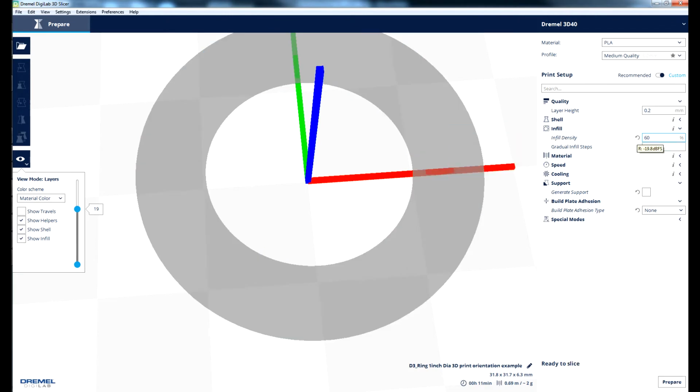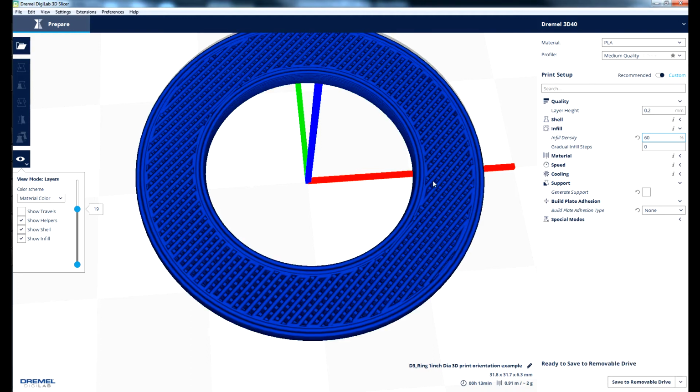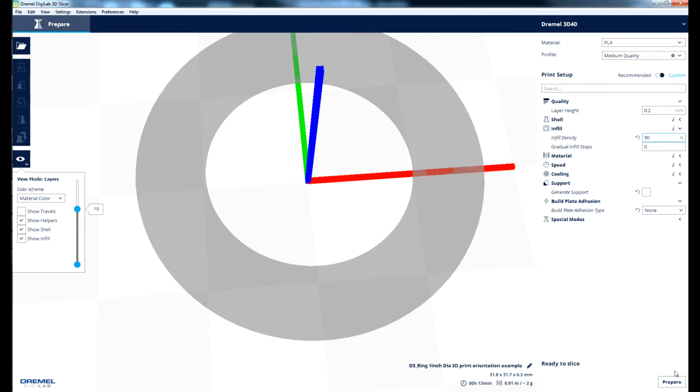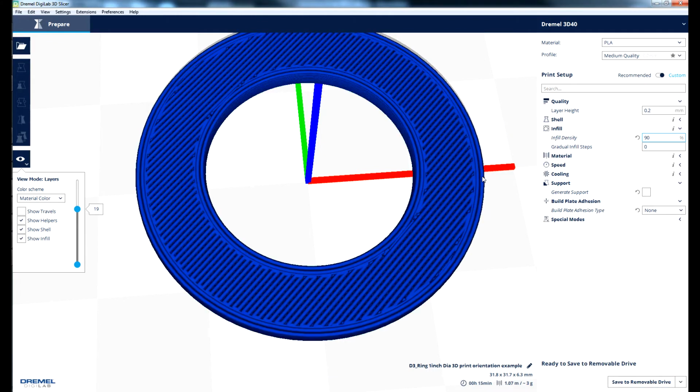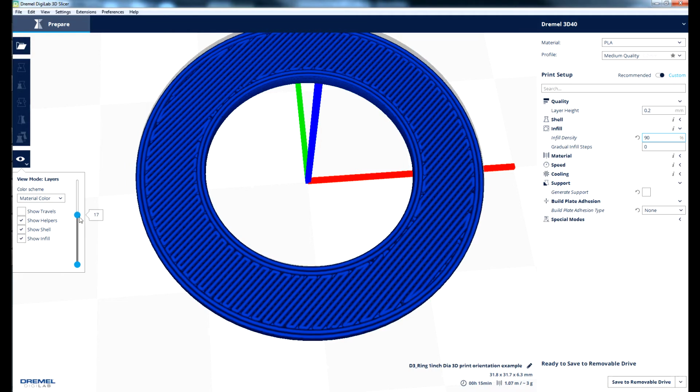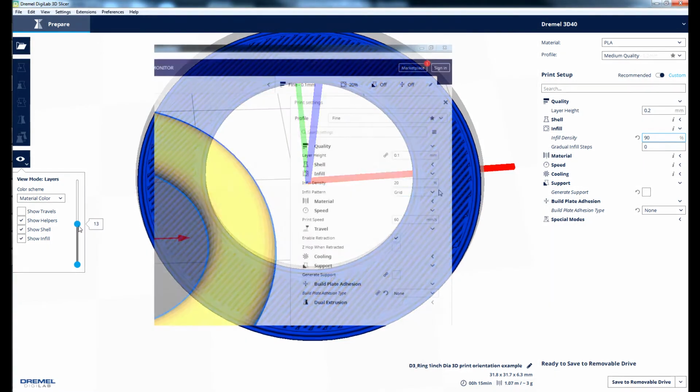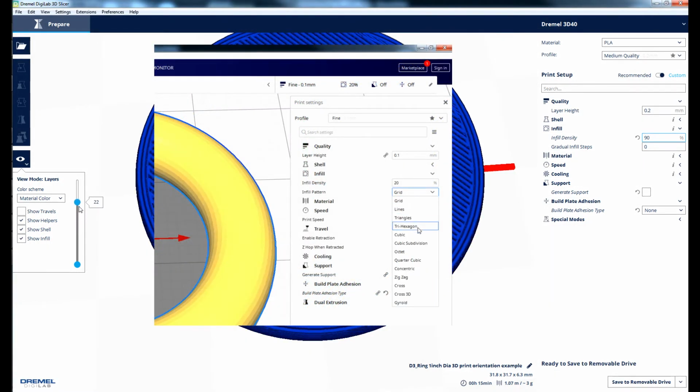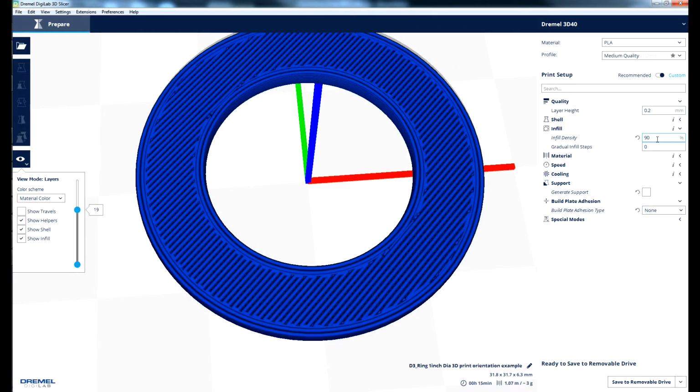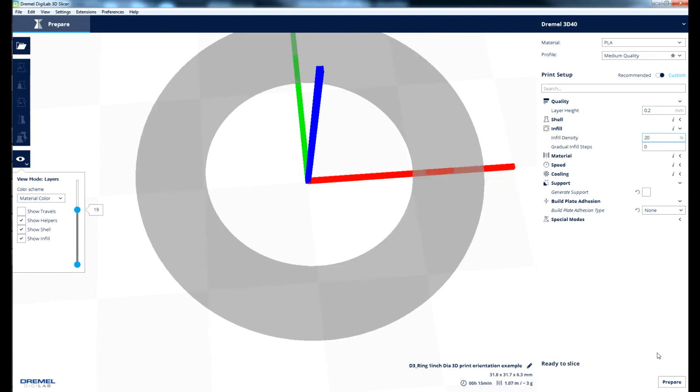The more infill, the longer the part takes to print and the more material that's consumed. Infill is the density across the entire part. Generally, a greater infill will improve the overall strength characteristics of your part. However, this benefit will start to plateau around 75% infill and up. Infill patterns are automatically generated by the slicer, though some slicers give you other options here. Cura, for example, has a wide variety of infill patterns best left for you to experiment with. However, the default infill pattern will typically work for most parts.